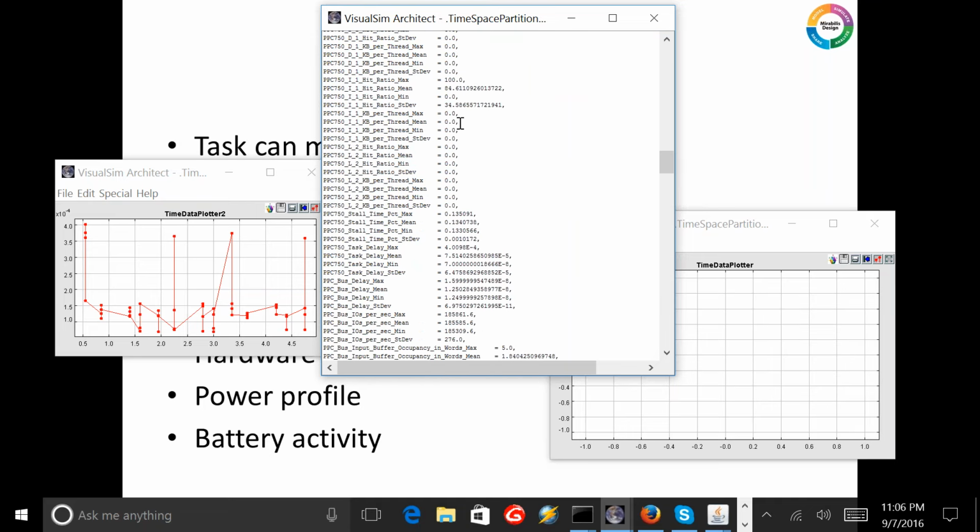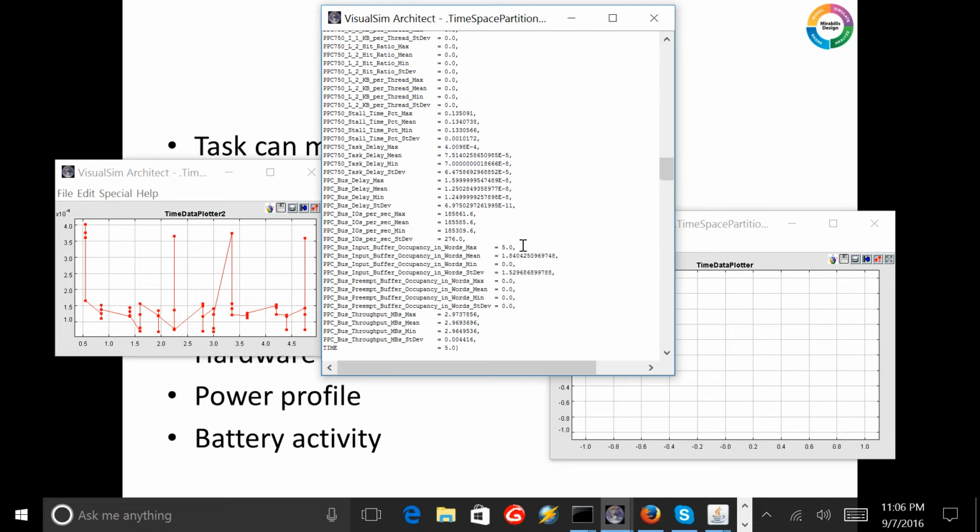The other aspect that I want to look at is my hit ratio. Notice I only have an 84% hit ratio on the iCache. So this tells me that the internal cache is insufficient. The application software is actually being loaded on and off, prefetching, and misses are going back and forth between the iCache and the external DRAM. So this is another reason for why you're starting to see this huge amount of backup, of buffering that's happening in the system, plus an extensive stall time.